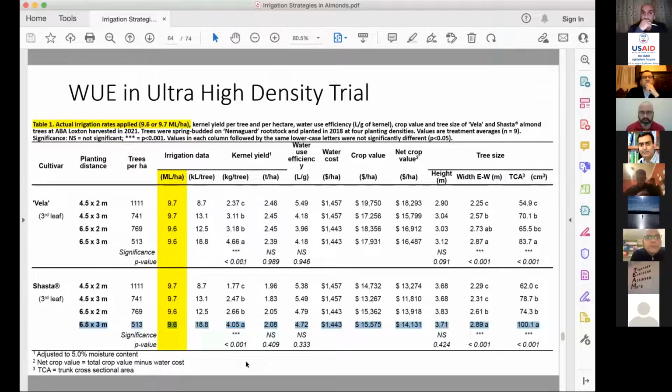Okay. Another question is about the drip lines. We are going to put the drip lines in the ground approximately 20 to 25 centimeters deep and approximately 1.5 meters away from the tree. That's because we are trying to take away the herbicide use in our orchards, and we are going to use some technique not to use any pesticides or herbicides in the orchard. What do you think about putting the drip lines in the ground?